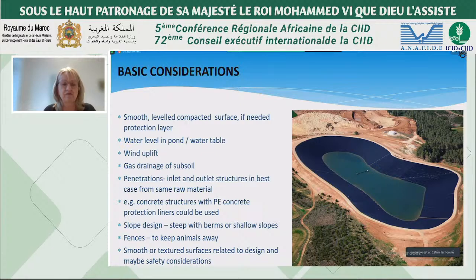The slope design is to be considered very carefully. It can be steep slopes, and then you have to think about berms in it, or you can have shallow slopes. A good measure is always, when you build such large ponds, and even if you build small ponds, to keep the animals away from such an application and to build fences.